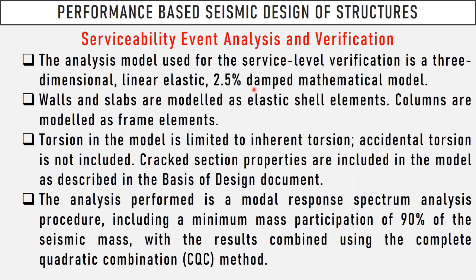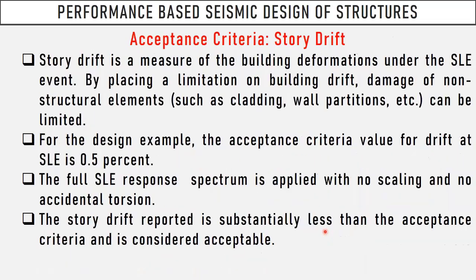Of course, again, cracked section properties are quite important. And while using modal response spectrum analysis, 90% modal mass participation is important.